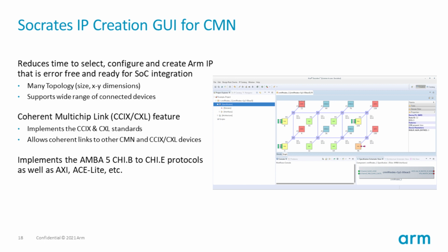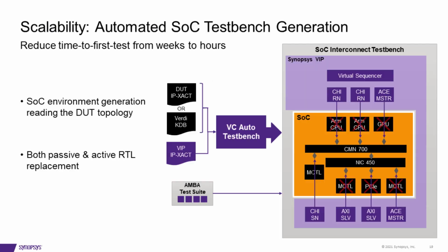Now, along with rendering the RTL or the Verilog code, this tool also provides an option to generate the IP-XACT for the design. Now, you can ask me what is an IP-XACT. For the benefit of all, IP-XACT is a standard defined by IEEE and Accellera, which is a language through which you can represent or define any circuit or any design or any block. So you can use the IP-XACT language to represent your SOC or your design. That way you get the design representation through the IP-XACT.